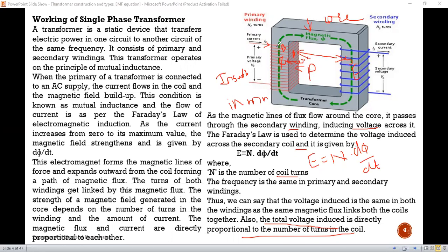And in between turns, insulation can be provided, either paper insulation or mica insulation. And you people know the winding is copper winding. Again, this copper winding can be varnished with some insulating material, or some thin coating can be used as a varnish. It will have varnish on it, or it has a coating. So this acts as an insulating material. Okay, so this is the insulating material. These three parts are important. One of them is the core, that is the magnetic core.